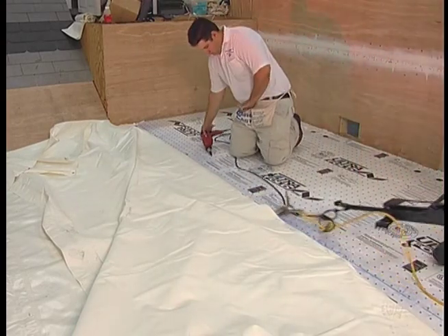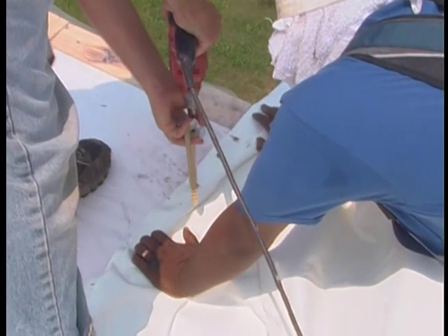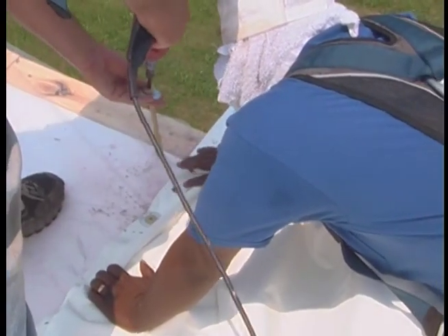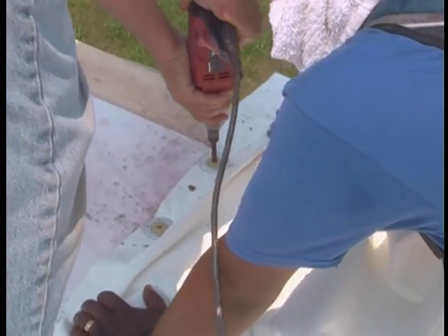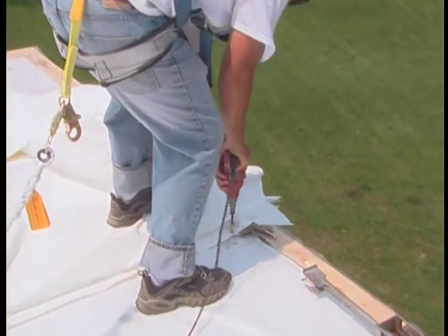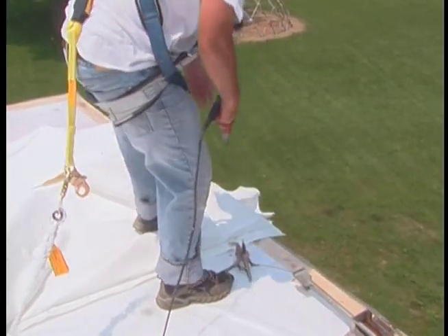and then go back and fill in the fasteners at the locations indicated on the tab. Another way to start the first tab is to use Duro-Last ratchet straps. After unrolling the deck sheet, position the edge of the first tab with the chalk mark and install 2 Duro-Last plates and fasteners near the end of the tab. Position the grip pole directly across from the screws and plates you just installed and pull the membrane tight. Install another fastener on this tab.